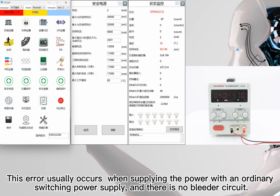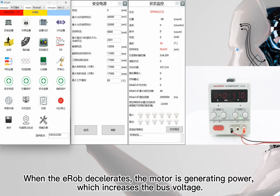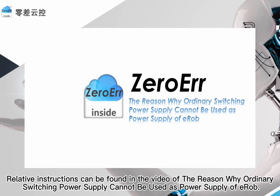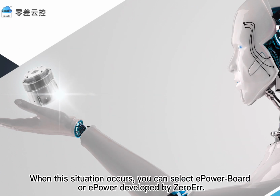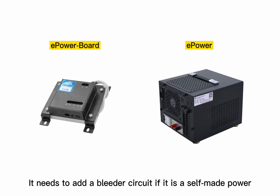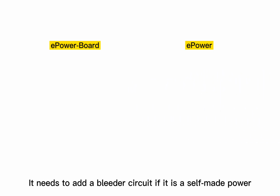This error usually occurs when supplying the power with an ordinary switching power supply, and there is no bleeder circuit. When the eRob decelerates, the motor is generating power, which increases the bus voltage. Relative instructions can be found in the video of the reason why ordinary switching power supply cannot be used as power supply of eRob. When this situation occurs, you can select ePower board or ePower developed by ZeroErr. It needs to add a bleeder circuit if it is a self-made power.